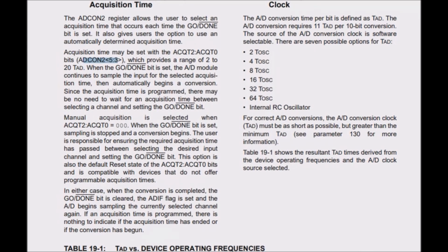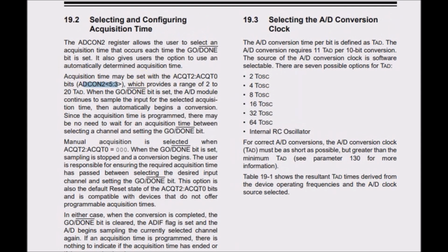If an acquisition time is programmed, there is nothing to indicate if the acquisition time has ended or if the conversion has begun. So I cut off the top there. So that was selecting and configuring acquisition time.